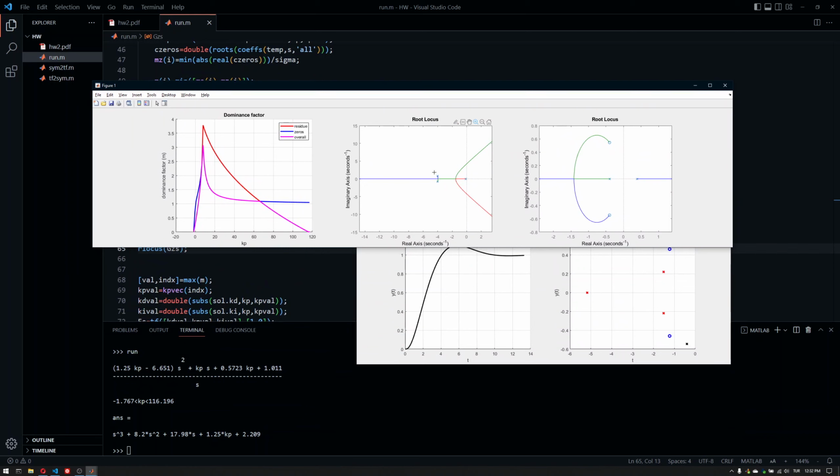This one belongs to the residual poles because I can count 3 poles here. And I can see that my point of interest, if I want to push everything away, is going to be this point here. So if I want to maximize the dominance for the poles, I would quickly choose this point because this is where all the poles are as far to the left as possible. Other than that, it will just enter back the plane on the right. But at this point, it is on the edge, or the corner of it.